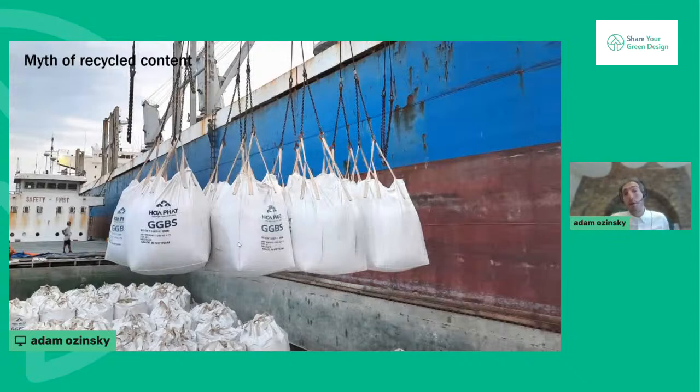This follows from the recycled content conversation. So again, I think this one's been around a while, which is this idea of using certain byproducts like GGBS, for example, as a cement replacement in concrete mixes. Again, in the UK, we are at the moment GGBS negative, so we depend on imports for GGBS. And the gist of it is that, like the scrap for recycled metals, the GGBS or the PFA or whatever these byproducts are, they will be used somewhere. So all we're doing is moving the displacement, but we're not actually displacing anything.